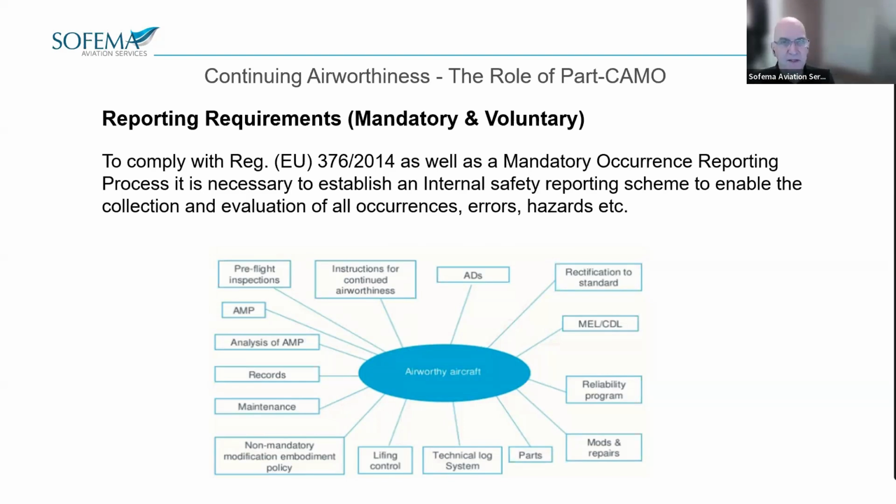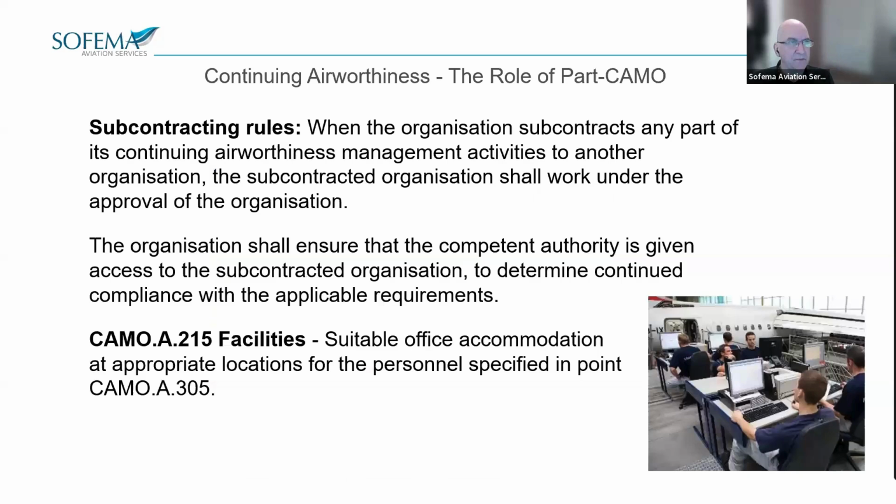And this would include items such as aircraft defects found during inspections, maintenance errors, for example, parts found incorrectly installed or missing, errors in technical instructions and work cards, excessive deferred defect rates, on-ground occurrences and incidents during maintenance and aircraft movements, injuries to personnel, quality audit findings, and airborne incidents of any nature, including heavy landings, structural damage, and engine and systems failures. Typically, these are collated within a single database administered by the safety manager.